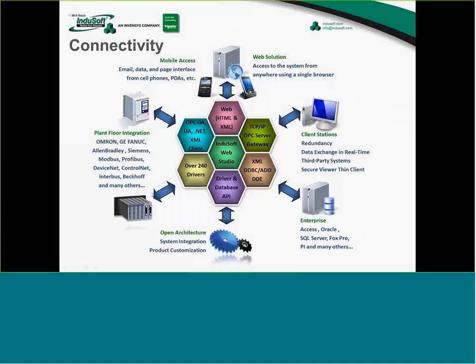We've got some legacy serial drivers out there for maybe temperature controllers or different drives, motion control systems, things of that nature. Think of maybe a temperature controller on an RS-485 network that you would never have imagined being able to get that information into a database. Now you can communicate directly to that device, get the information into InduSoft tags, and now out to a database.